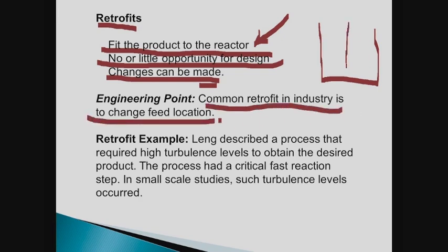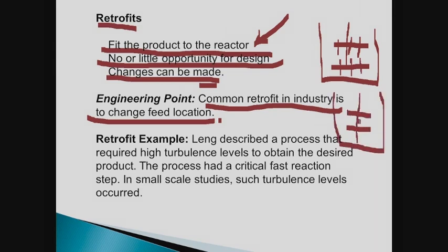For example, in gas-liquid systems, everybody used these flat blade impellers, and now they've turned to the Smith impeller. At least some people have. Not all, some. Where you have the curve. That would be a retrofit, right?